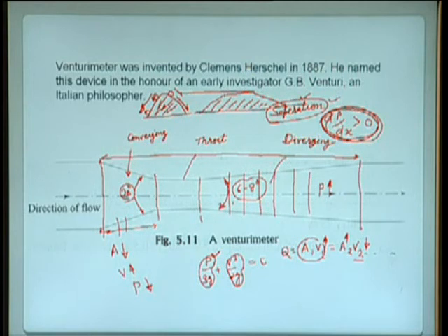By reducing the angle, we increase the length needed to achieve the same diameter. Whenever length is increased, as we will study in a subsequent lecture, the fluid has to travel more distance, and there will be frictional loss, because whenever a real fluid flows in a pipe there is frictional loss, and to overcome it there will be some pressure loss.